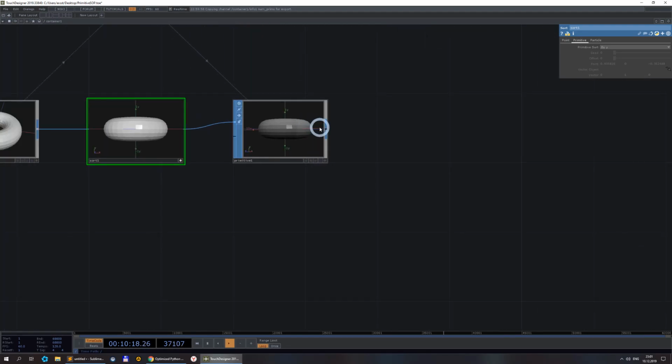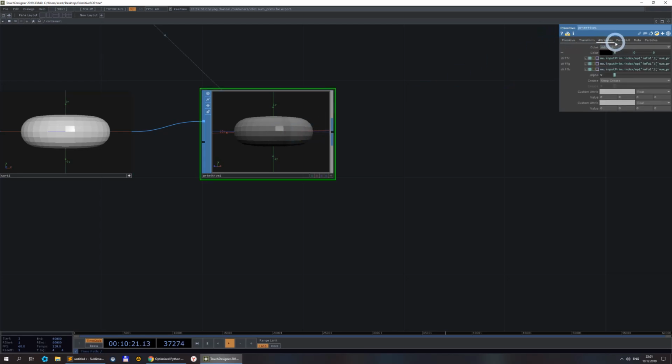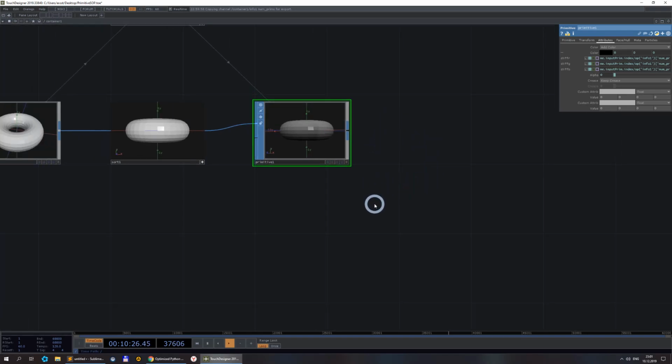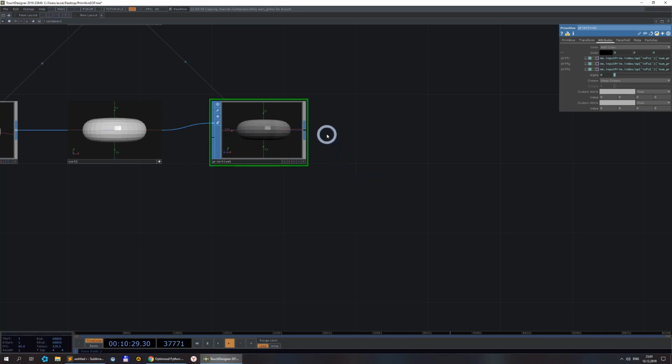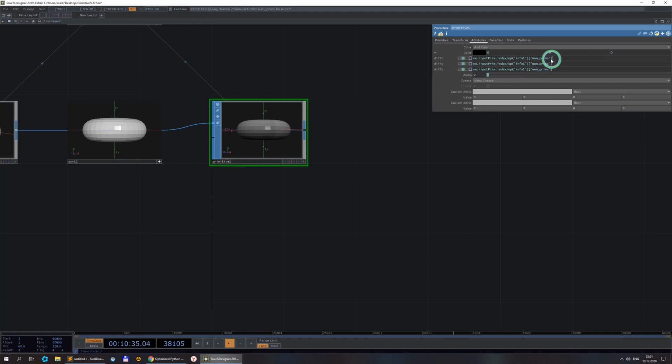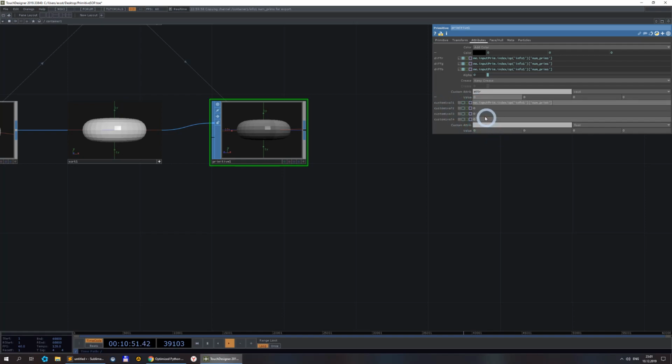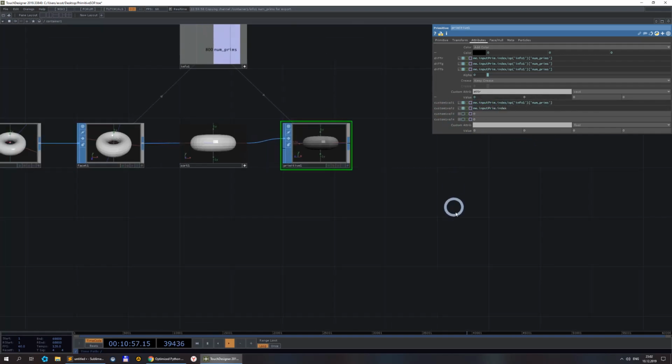And a good trick you could use here is you could add your attributes, and it will allow you to show any of the values you have here. For example, I can create an attribute. Let me add some. I just call it attr. Set this to vec4, so it keeps 4 values. And in one I put our color. In another, to show you, I'll just put what is input primitive index.